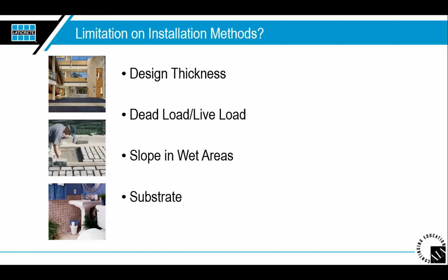And I've always, in my past, understood that you can do a direct bond application interior to wood. And really putting the study into that, and again, going back to the TCNA manual, you will find that just because you have a 3/4 inch exterior grade plywood down on the substrate, it still needs a secondary layer. And that's not even for a natural stone installation where we commonly see that, but you need that secondary layer to actually act as the underlayment. So understanding substrate versus underlayment, and those terms are actually defined in the index of the TCNA manual. So again, we'll go back to that as often as possible when we're looking for definition of installation.